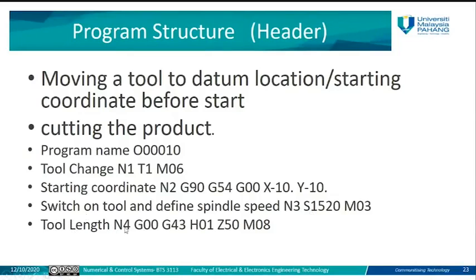Tool length, for example, here G00, as we mentioned before, G43, H01, we are going to consider the tool length, or the length of the spindle, I mean, the tool which is attached to the spindle here. We need to define all these in the header, or the setup, of the program.